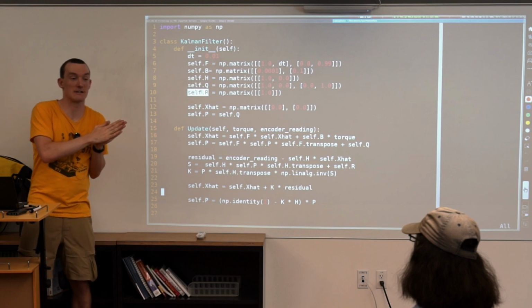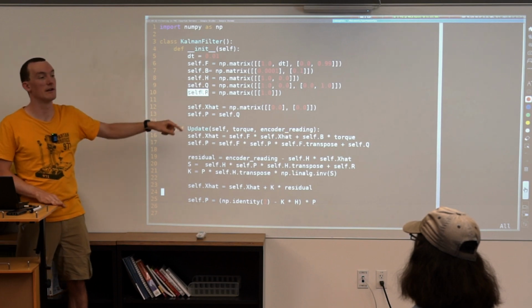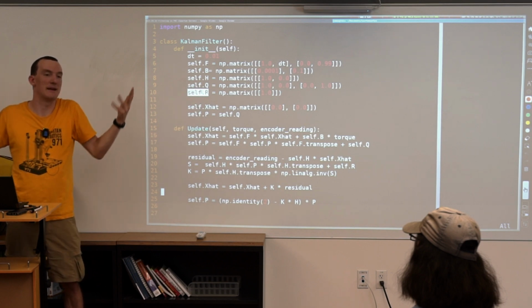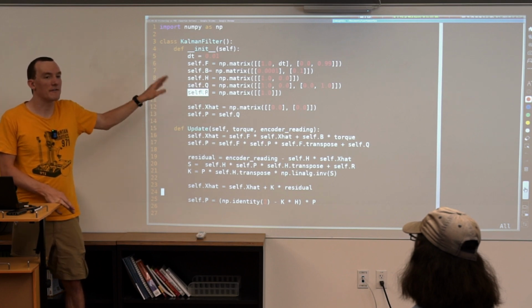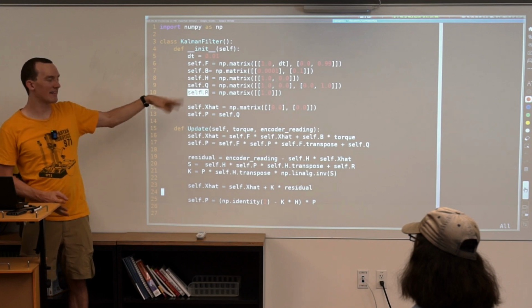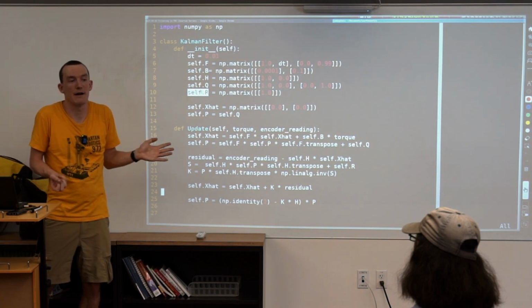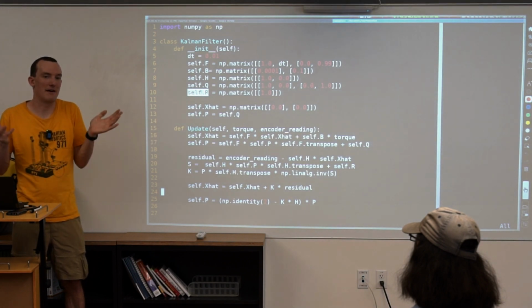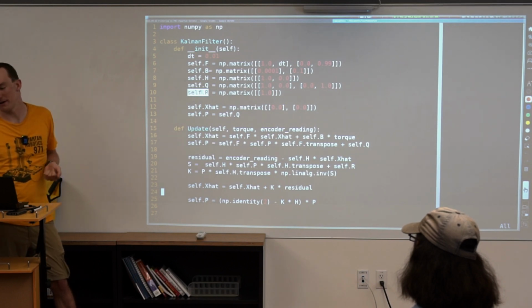And that's why the prior Spartan series talks include discussion of that, because those are about the control loops themselves, less so the estimation. Once you have those numbers, you just feed them in and you get a pretty good estimate to begin with. We don't end up having to spend a lot of time tuning this for most mechanisms. We spend a lot more time on localization and such, but for most mechanisms, it's get the numbers about right and it's pretty good. That's in part because encoders are very good to begin with. Yes, they have some noise when you're estimating velocity, but beyond that, if you have a decent encoder and your mechanism is stiff and has low backlash, then you're in a pretty good state to begin with.